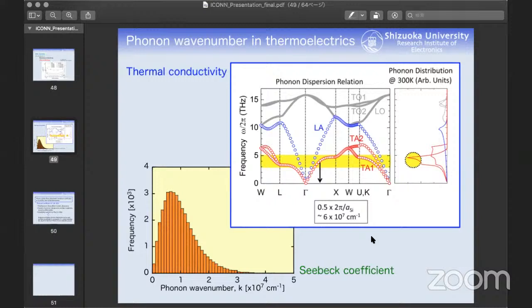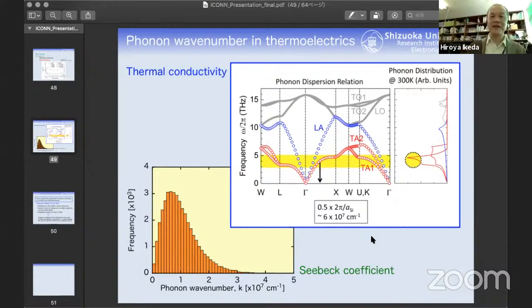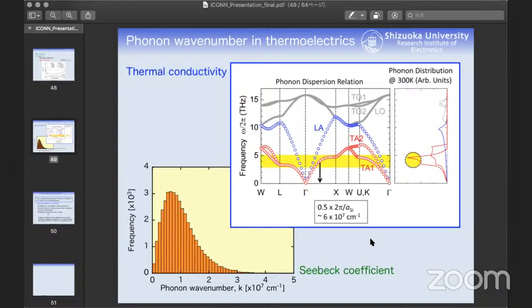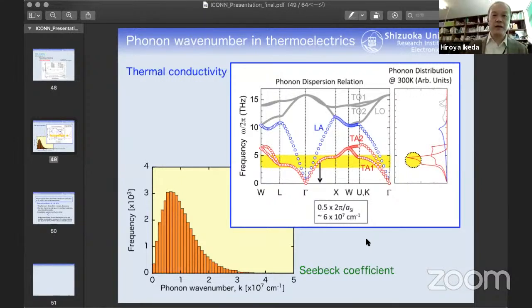Yeah. So that's why I need to ask: how much is the carrier concentration in your sample? It's around 10^19 to 10^20, it's 10^20. It's a p-type material. Yeah. So I think electrical conductivity, as you know, strongly depends not only on carrier concentration, but also on the effective mass of the carrier.